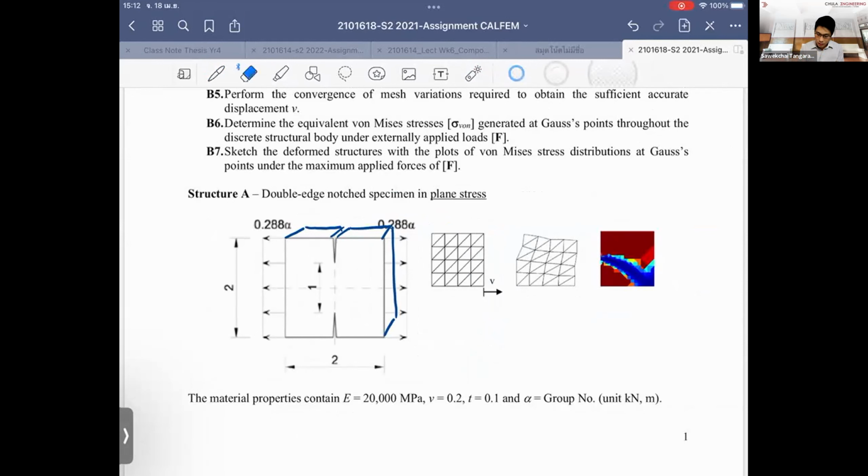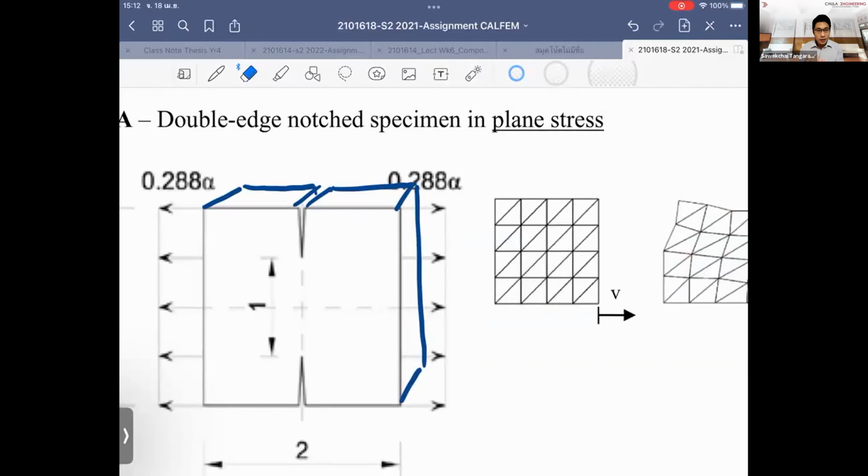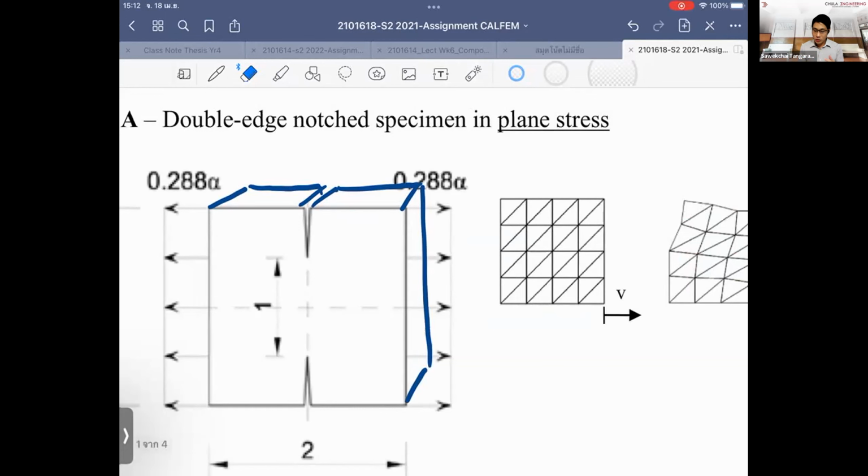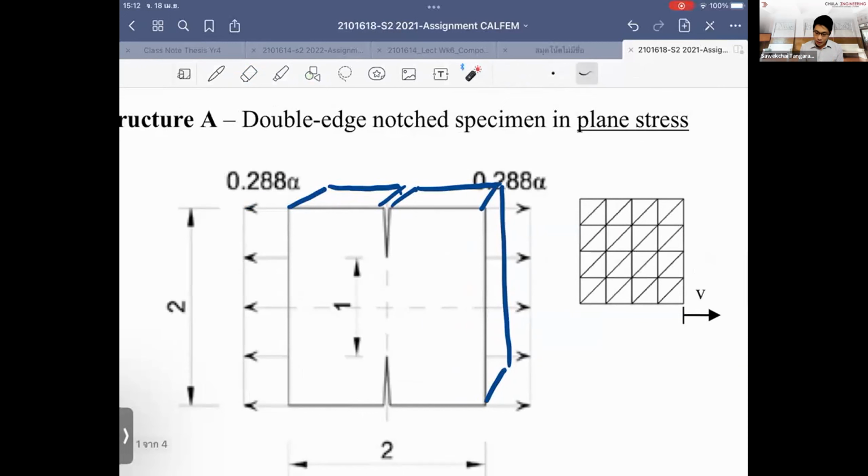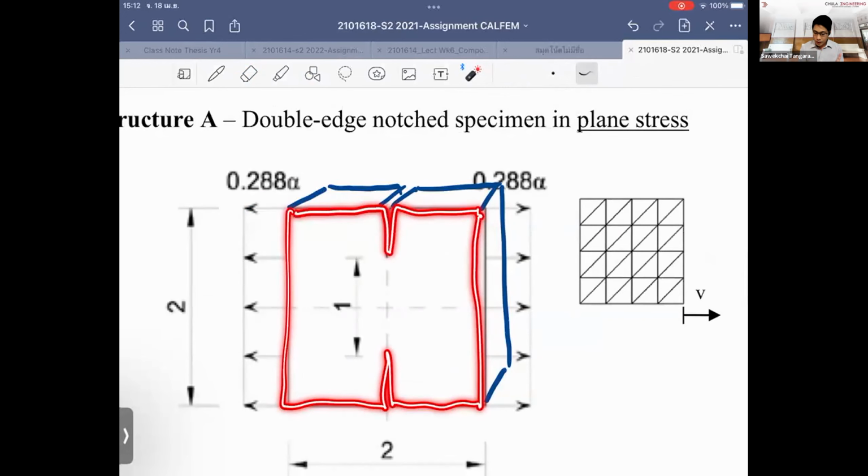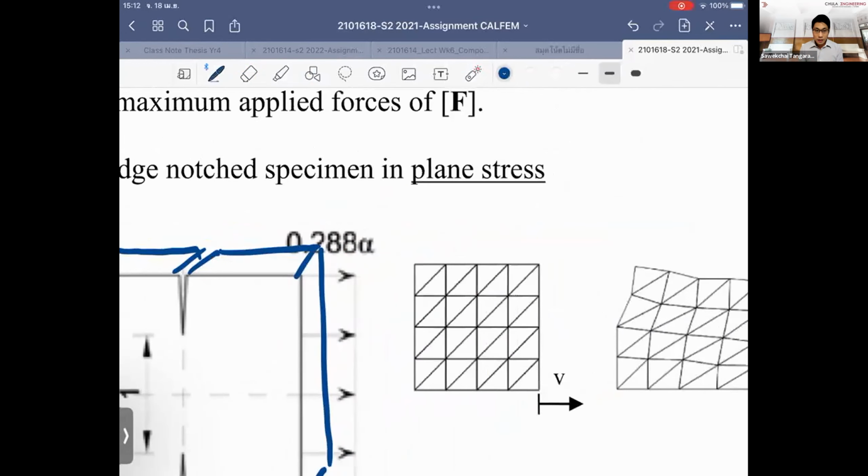When we say it's very thin, what we're saying is that the stress in the perpendicular direction is 0, because we allow the stress to transfer only within a plane. So it means we try to project the structure within a 2-dimensional plane. And in this plane, we're saying that the stress in the perpendicular direction to the plane is equal to 0. That's why I'm saying that sigma, which is the stress in the z direction, is perpendicular to the plane.